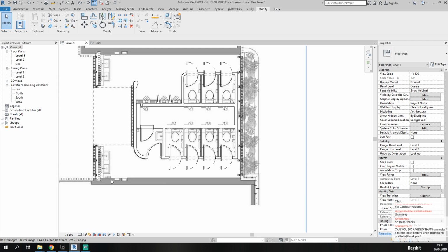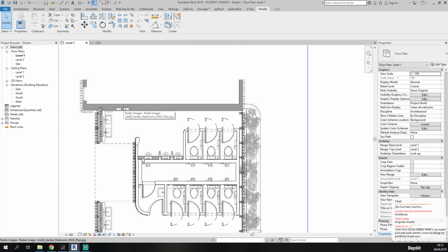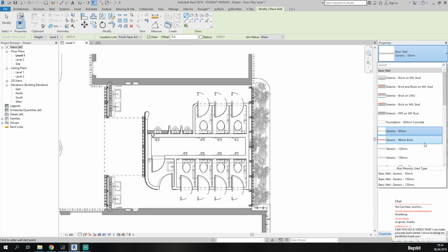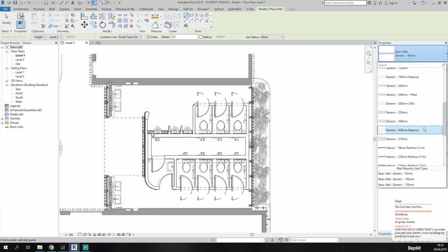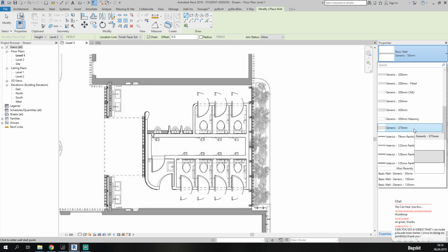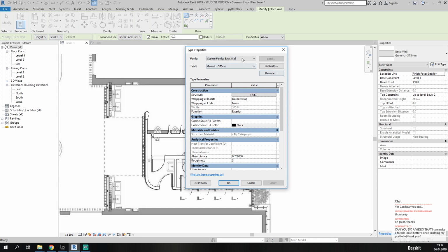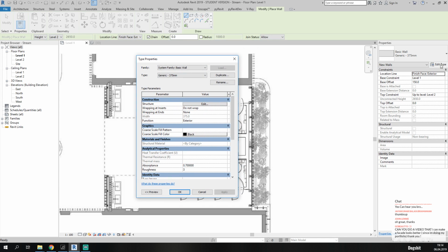So let's create this door, this wall, and that wall. It's already the other building, but we just need this wall to make this more understandable. Let's go to the architecture. I will use some generic wall, a really white generic wall. I have only 375 millimeters, but let's create 500 millimeters. Why not? You just go inside this family, to the type, and after that duplicate. Don't forget about duplicate, guys, please. You should do that. And let's create the 500 millimeters here.